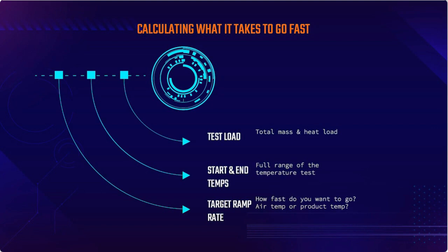This ramp rate may be measured on product or as air temperature ramp rate. Most performance chambers have the ability to test based on the sample's temperature. With heat generating or large products, this can be a complex decision and worthy of some experimentation. We're pretty cautious about doing on-product rate calculations because of the wide variation of rates depending on the exact sensor placement.